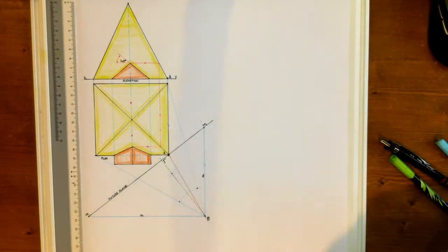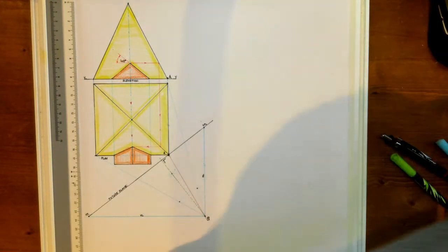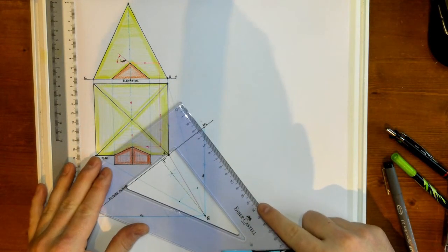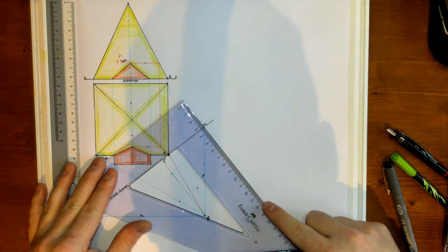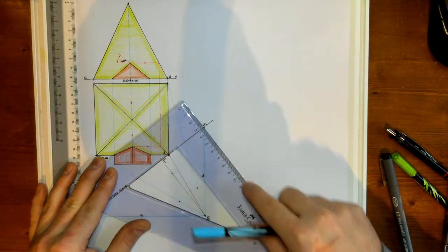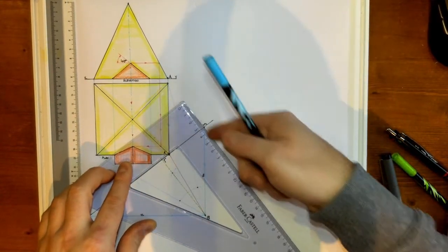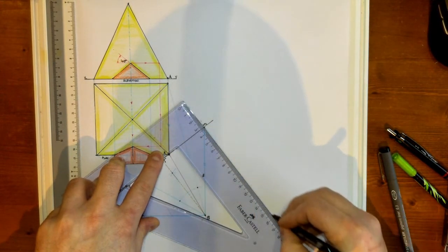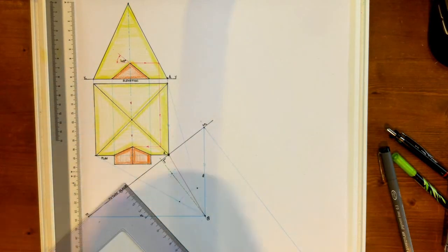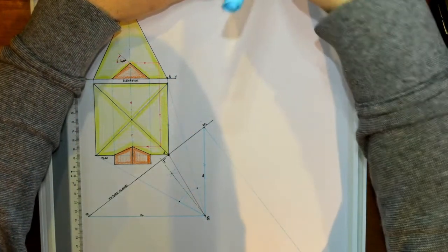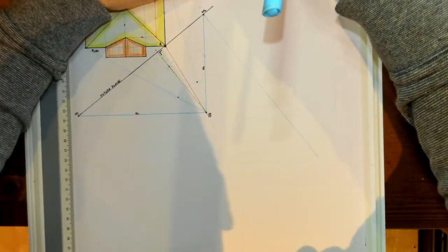So I'm going to move this fella over here, and I'm going to get my set square, and again I'm going to use my little line technique here. I'm going to line up the inside of the set square with the picture plane like so, and I'm going to line up the outside line with VP2 in this case. I'm going to draw that line on down there. Don't worry about the length of it, just draw it on down. Okay, I'm going to adjust my visualizer now so that we can get in view of the rest of it there.